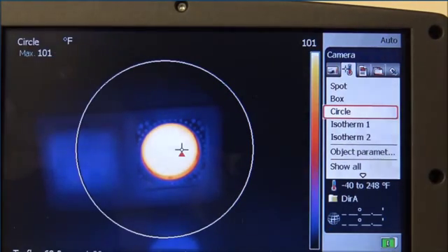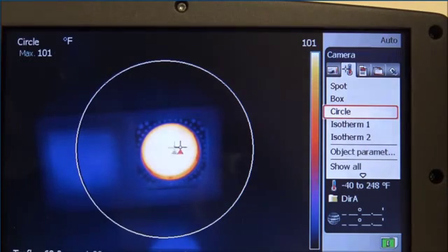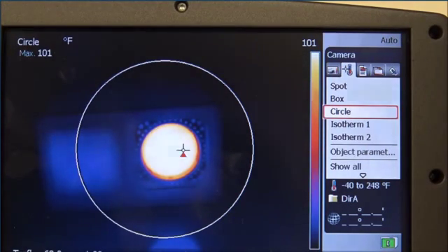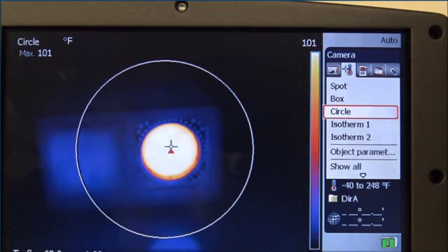This video is going to show just how we can compensate for an infrared window using infrared window transmittance, a bit like the coffee cup test, what we call in Iris. If you look at the image now, what you can see is the viewfinder of the camera. I'm looking at a black body, but this could be any hot surface, such as a cup of coffee, with a known emissivity.